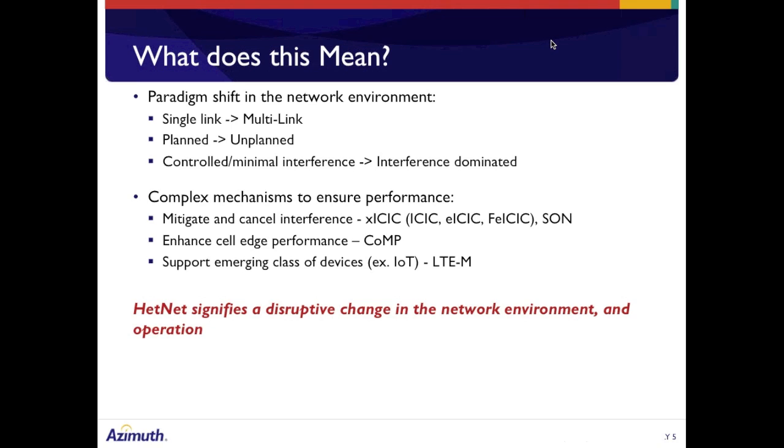And because we have our single frequency network here, we end up with a lot of interference. Now, interference was always a big deal even in the older days of higher frequency reuse of, say, frequency reuse 7, where you had 7 different frequencies around your hexagonal layout. But now, since there's only one frequency and everything is so much closer together, the interference is not so easily mitigated.